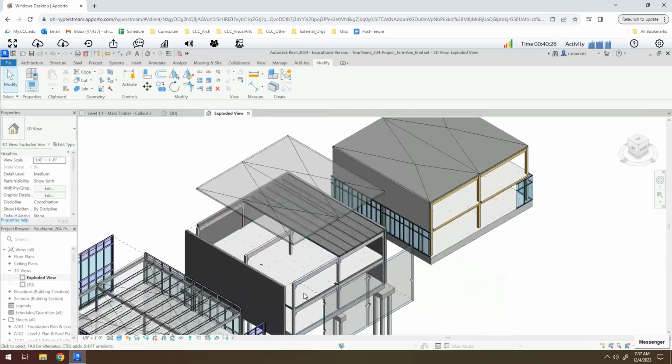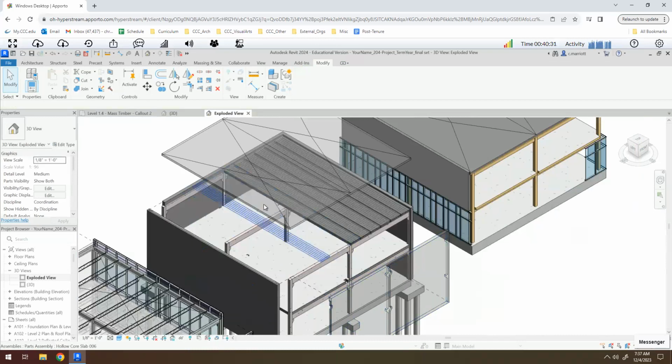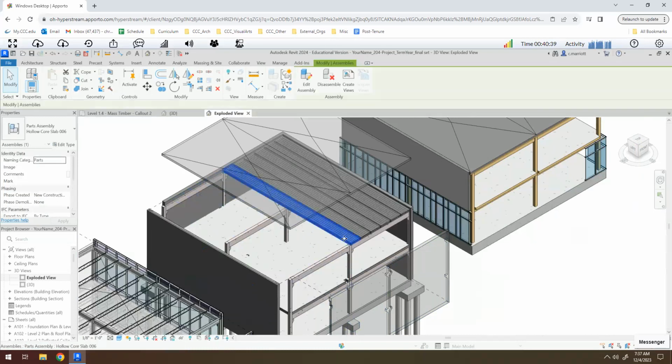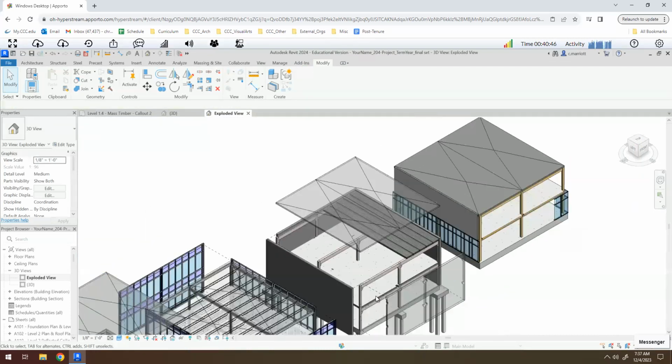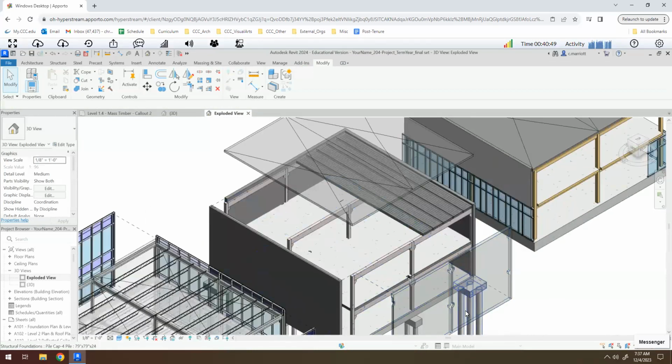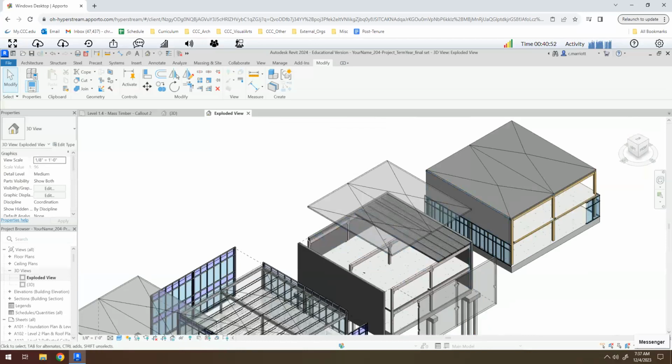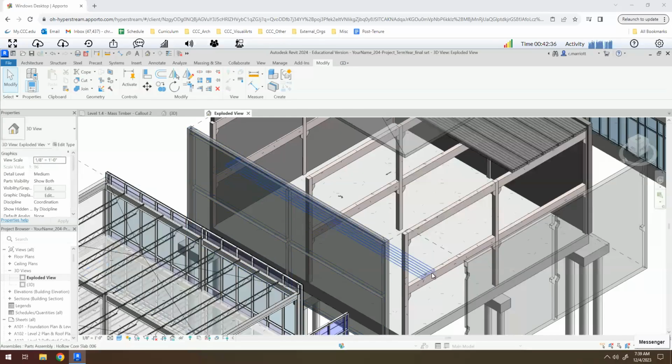But what I want to happen is that I can see some of these precast columns and the corbels on top. So maybe it's best to hide one more of these in my case. Of course, you can show what you want to show with yours. And I can continue to tweak this one and the last one over there. One word of caution is to make sure that you don't actually delete anything, because you can hide them in the view, but if you eliminate something, it's going to be eliminated from the whole model.